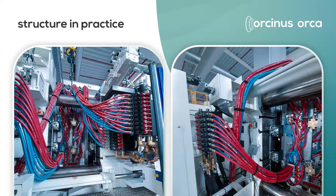And here you have an additional supplement, multi-coupling, which makes the process really reproducible, because every time you have a mold change, the distance from the manifold to the mold is the same because you always use the same length of hoses. You always have the same diameter of hoses. So the pressure drop and the heat loss are always the same.